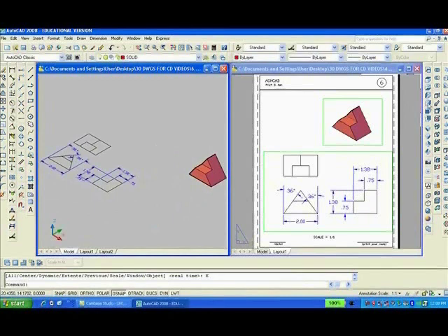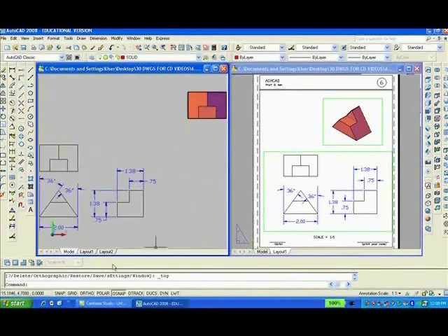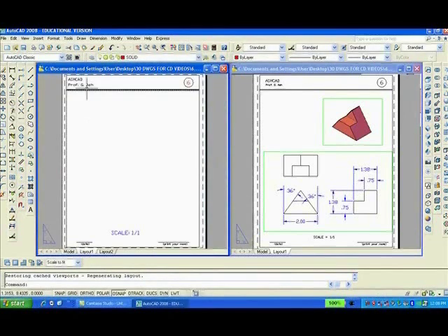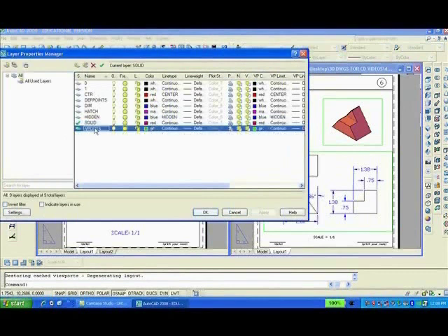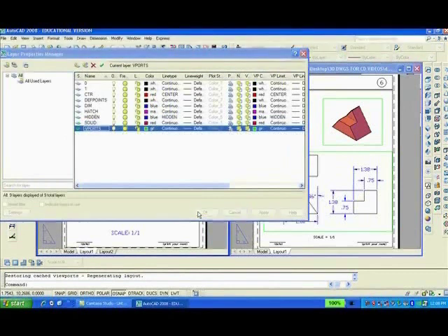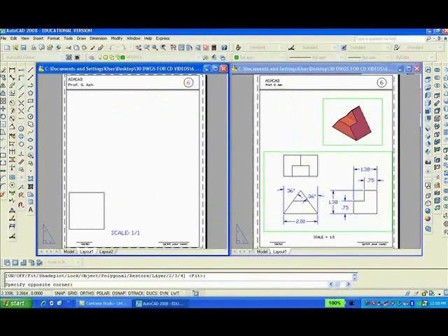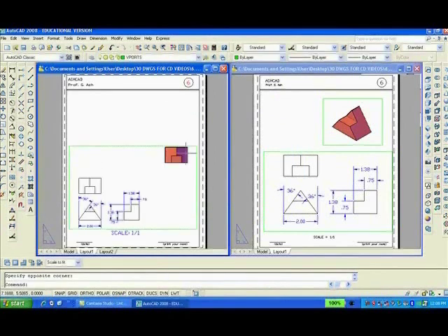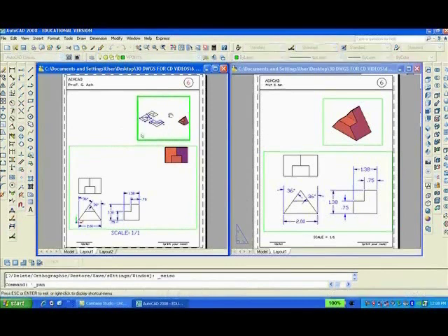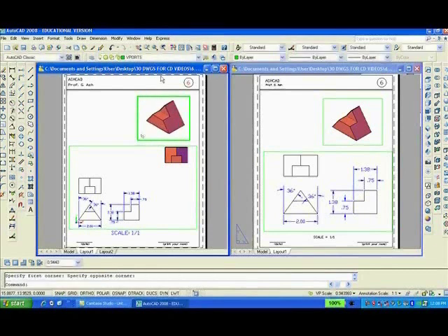move to top view, click on layout button, click on layer button and make layer viewport current, take off full snap, type MV, enter, make a large window, enter, make a smaller window, enter, double click inside the small window, go to southeast isometric, pan and zoom, pan, zoom, and zoom some more with real time.